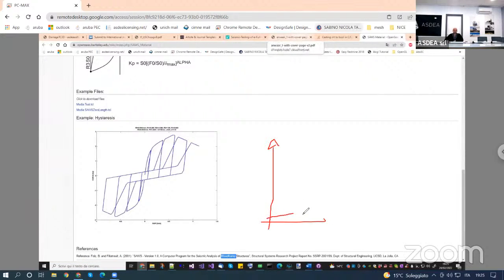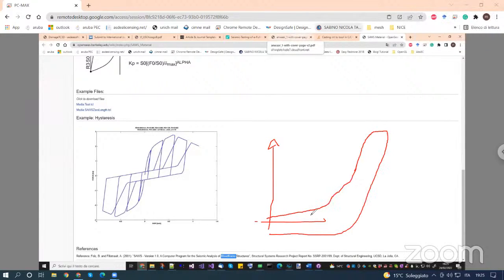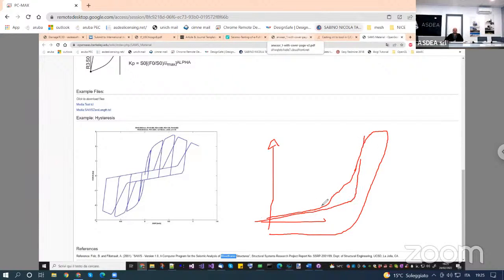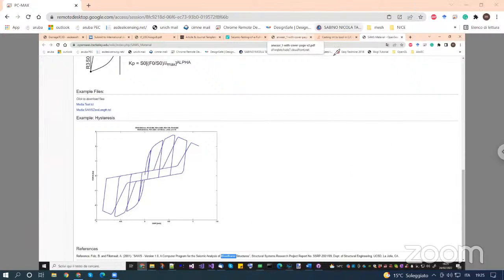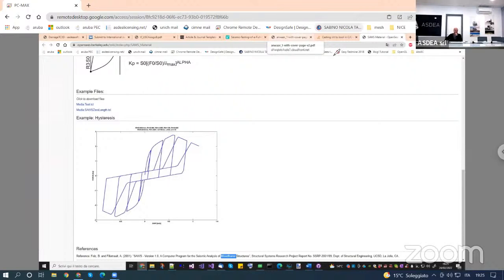It starts, then it gains some stiffness, even from the very beginning. Is it right? Something that goes in contact and then it goes upward. I don't know if there is something in OpenSees. Probably you can simulate it with a gap element, because there is a gap elastoplastic element, and then you can add a little bit of strain hardening, I think.